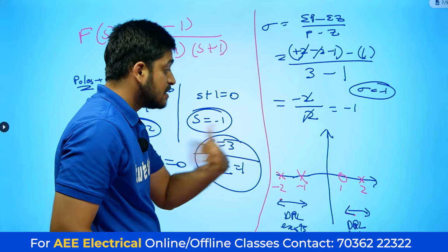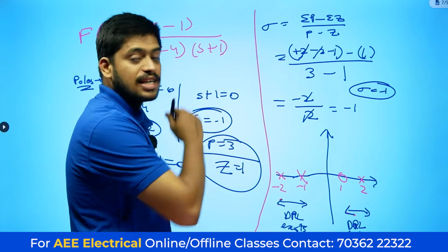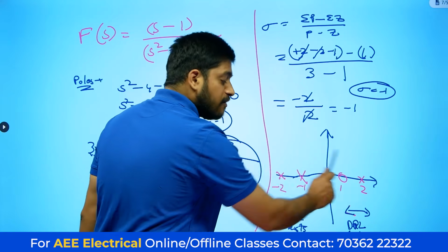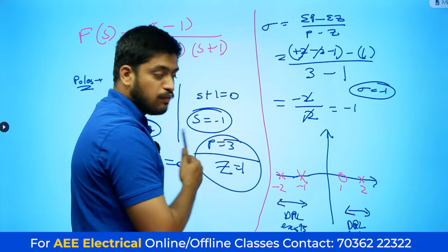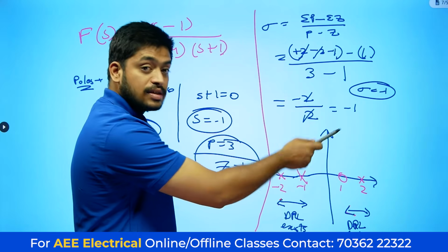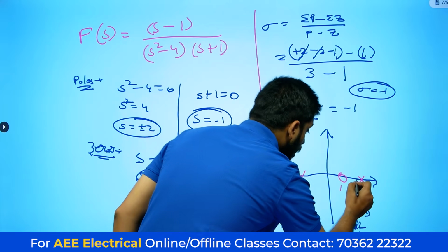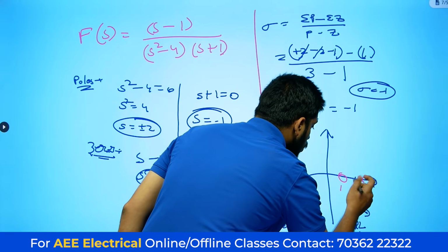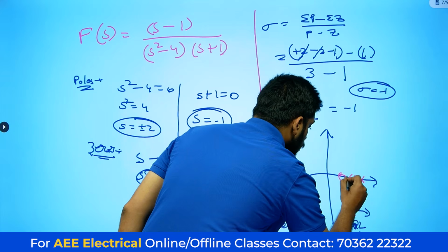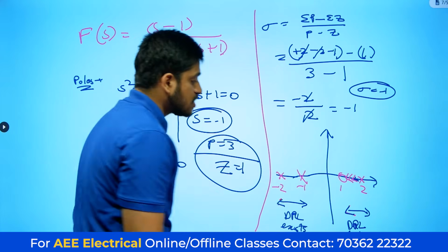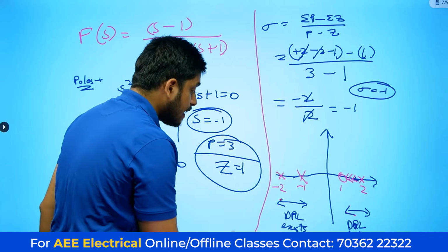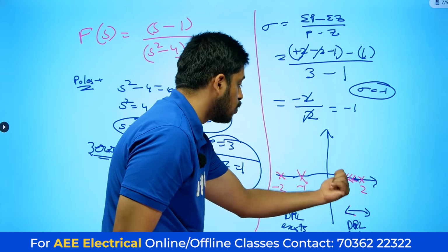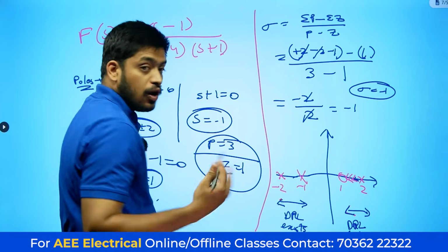Next, let us see in which direction the root locus goes. We know that from one open loop pole, the root locus is going to go towards 1. Why 1? Because it is an open loop zero. So here our way would be 1 pole to 1 zero. This is the direction of 2 to 1, from open loop pole to open loop zero. Here also the root locus exists from pole to zero. But here, pole to pole, how?